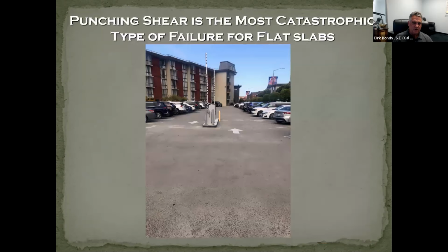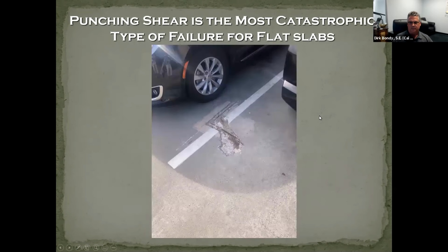Now, this is an interesting structure, particularly given the Surfside situation. This was a building, a hotel, it's changed names, in San Francisco. We did this in 2003, so this was 18 years ago. But not unlike the Surfside condominiums, where there is a tower portion and a slab that extends out one level well beyond that tower portion, but also goes back underneath. So they're connected. Again, there were signs that the concrete had kind of been thinning on top and whatever exposed rebar was starting to make its way out.